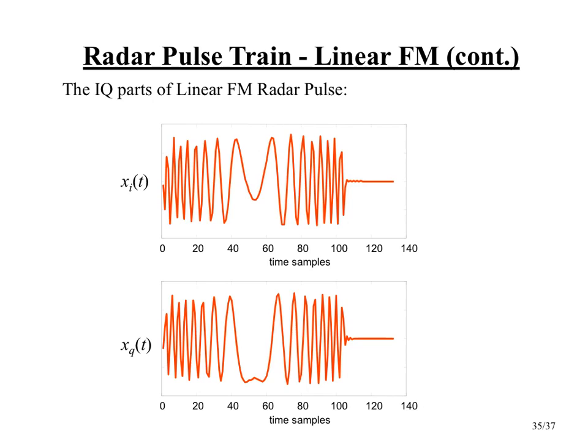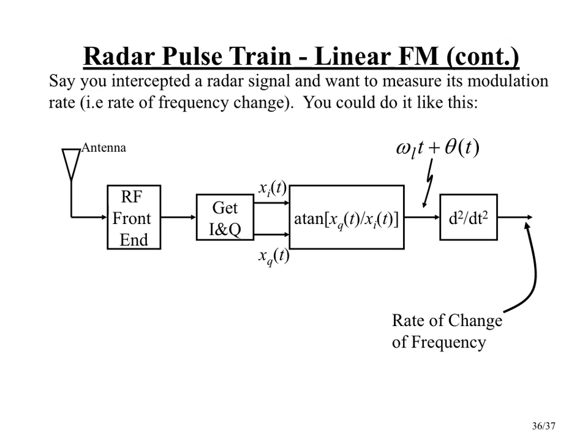So if you use that structure, use the equations that we just talked about, and you set up the phase following that quadratic and put in the small carrier offset, and you compute this in MATLAB, you can actually get a plot of what the I component and Q component look like for a particular given case. So this is just a plot of that.